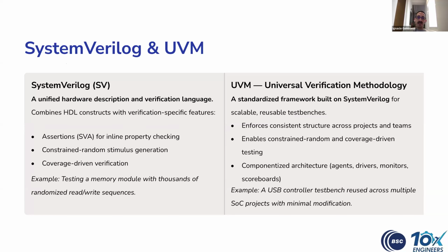It combines HDL constructs with verification-specific features, with SystemVerilog assertions, constraint randomization, object-oriented programming, and coverage-driven verification. So UVM gives a blueprint for building the components of that layered architecture test bench that we saw. Agents, drivers, monitors, scoreboards. It is heavily focused on reusability and on constraint random verification.